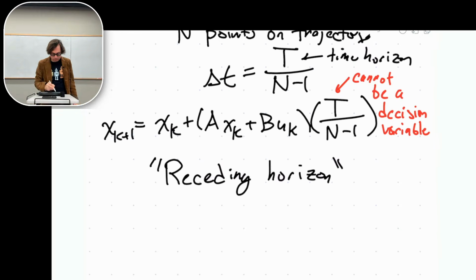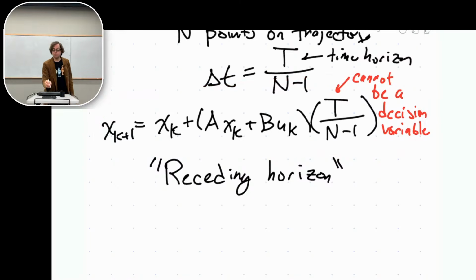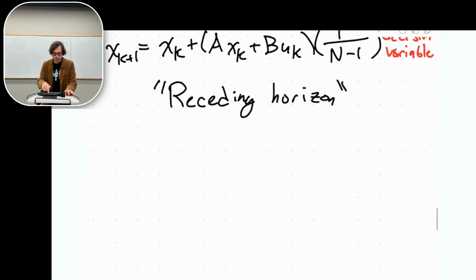So that's your constraint for MPC. If you have linear dynamics, LTI makes it easy. Theoretically, you can get away with linear time varying. That's something you can do, though we haven't covered that yet. But that's your LTI dynamics. And guess what? Linear constraints for your trajectory optimization problem.